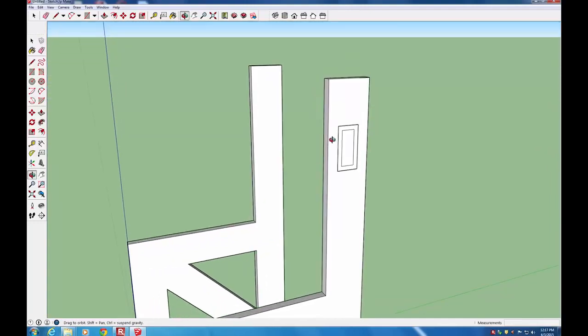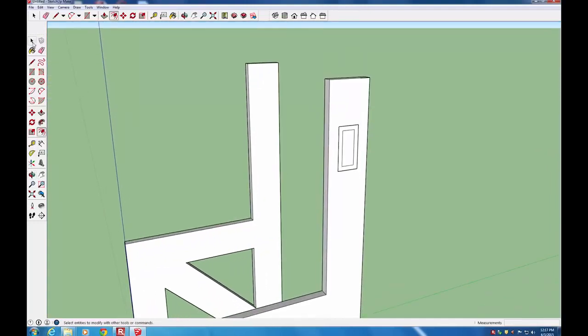And I'm going to rotate so we can see the push-pull that we're going to do next. So first, I'm going to delete this middle face of the rectangle here, and then select the push-pull tool. Hover over the section that we want to push, and then start moving that. And what I want to do, I want to make it stick to this opposite side of the chair piece. I don't need to go all the way through. So we just click, and it's there.